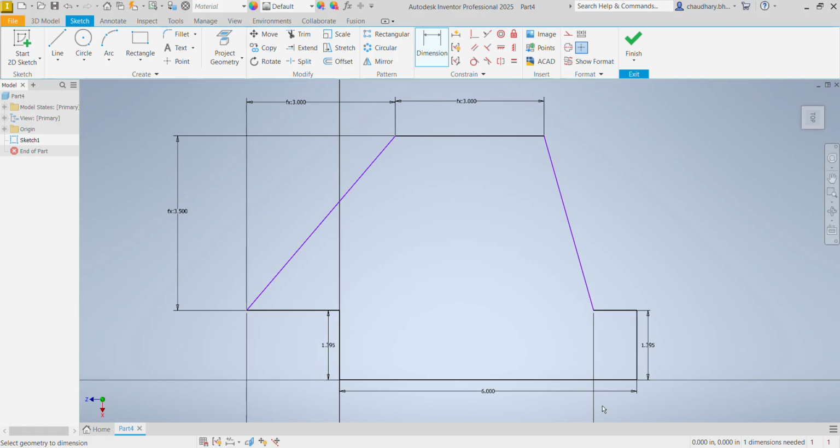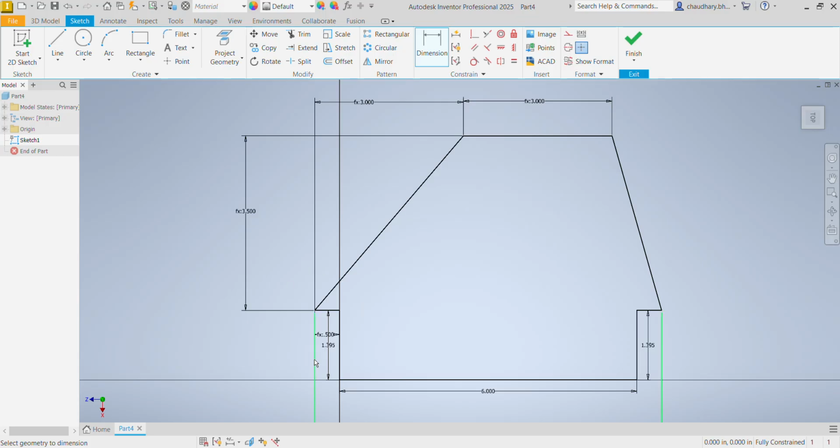So it's centered. If we have our fin tab as centered, we can actually dimension our overhang with the equation root chord minus our fin tab length, which is 6, divided by 2. That's for a centered fin tab.